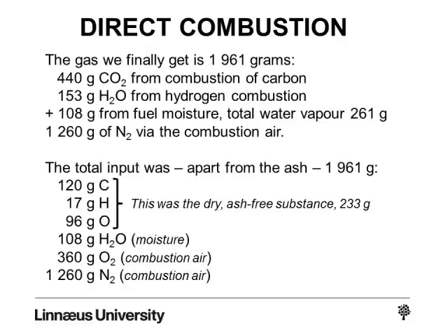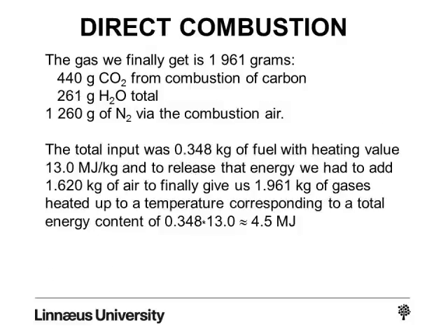The total mass balance, as shown in this slide, always has to be fulfilled, so that all the mass that we input into the reactor has to come out of the reactor. So it's always a good thing when you want to do this type of calculations to add up all the input and all the output and check that it fits. And as you will see from this slide, it fits in this case. But there is not only a mass balance to be fulfilled, there is also an energy balance to be fulfilled.